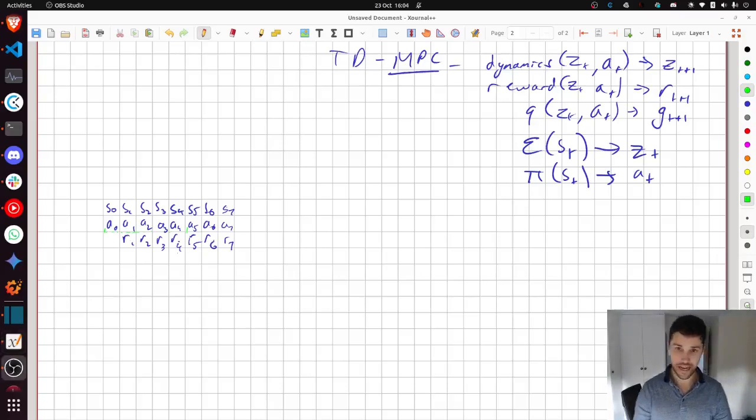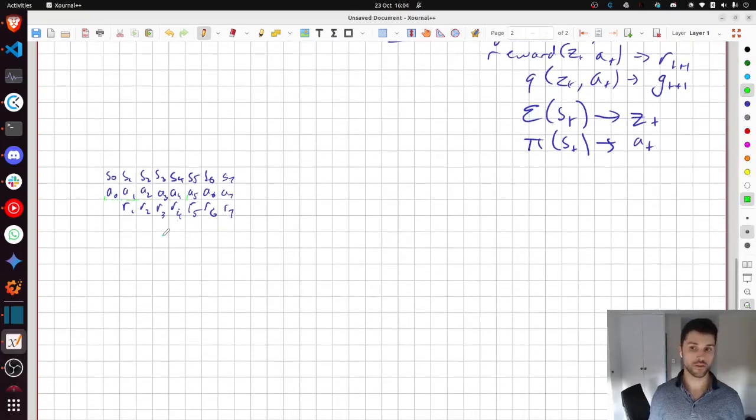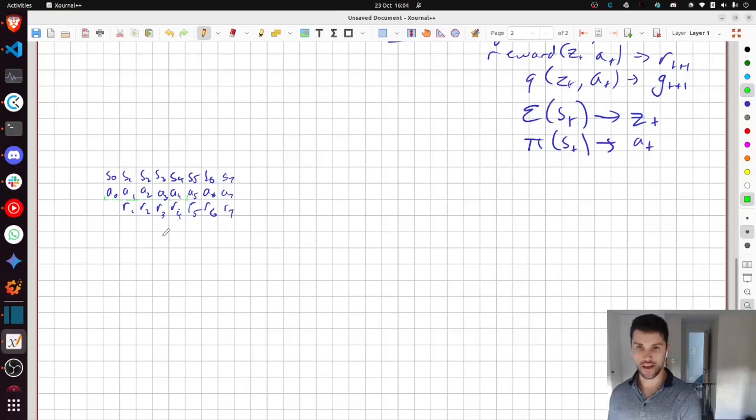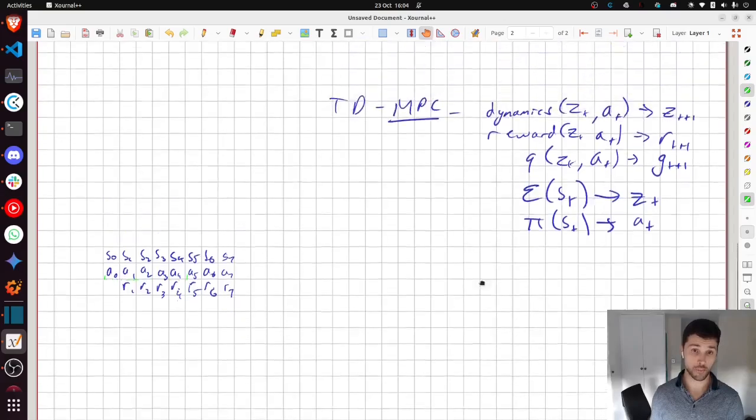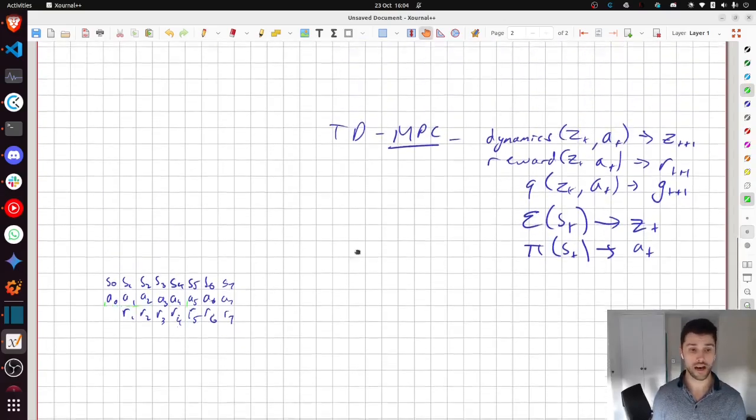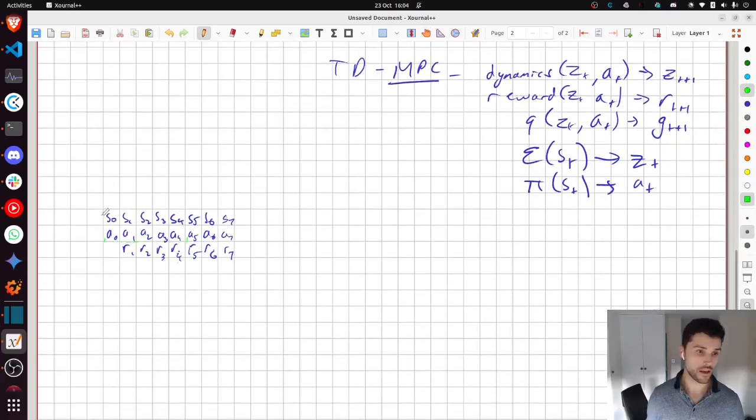Right, so now speaking of the data set, let's just understand what that looks like. There are two ways that the data set comes about here. One is you've either pre-recorded some demonstrations, that's actually an optional part, and then the actual part that's in the TD-MPC training loop is every now and then, in between training network updates, there's a step where the robot actually runs rollouts using MPC with these neural networks here, and we record that as we go.